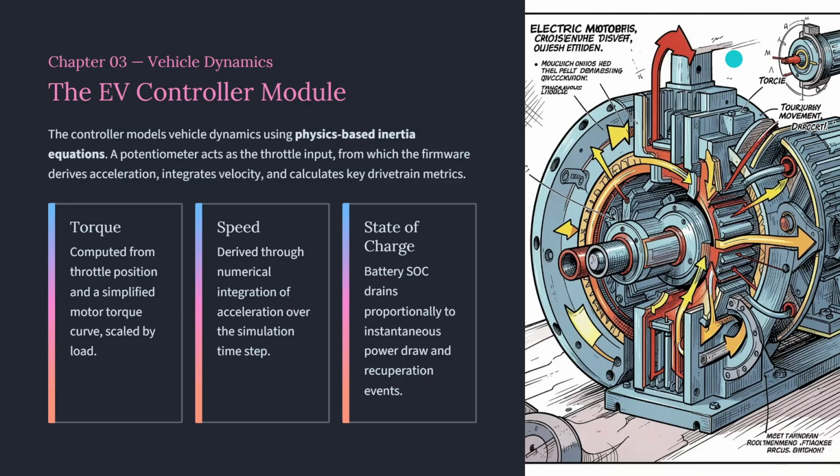And the next is driving mode, such as eco, normal, and sport. Eco mode limits torque output, so even high throttle results in slower acceleration. Sport mode increases torque gain, making the vehicle respond aggressively, even for small pedal input. Normal mode balances both.